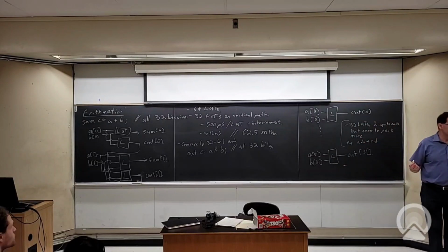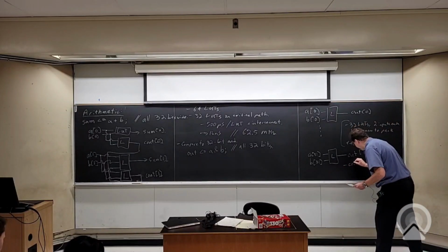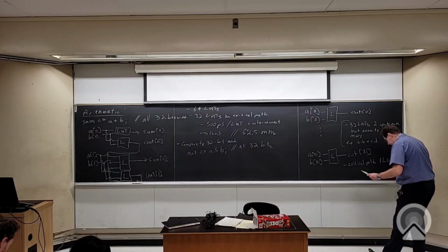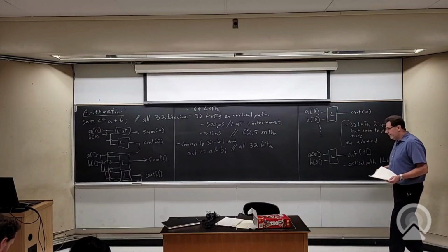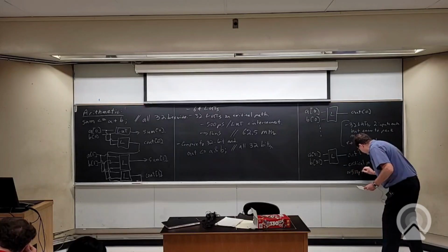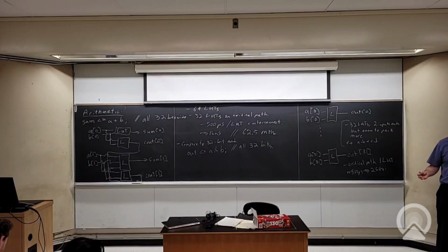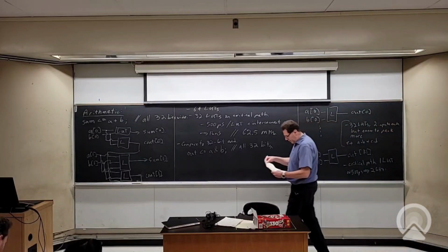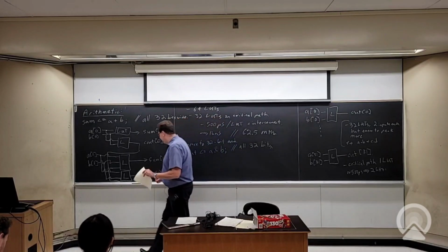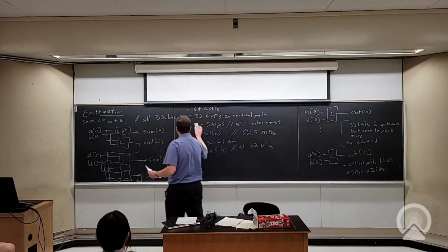What's my critical path? Yeah, so the critical path is the really big difference. The critical path is 1 LUT. Okay, so with my same estimate of how fast a LUT is plus the interconnect, I get basically 500 picoseconds or 2 gigahertz. Okay, so this is a pretty simple operation, but it's not speed limiting, right? Like I've got no problems with speed here, but I already had a problem with my adder and speed. Okay, so let's see, let's get rid of this.